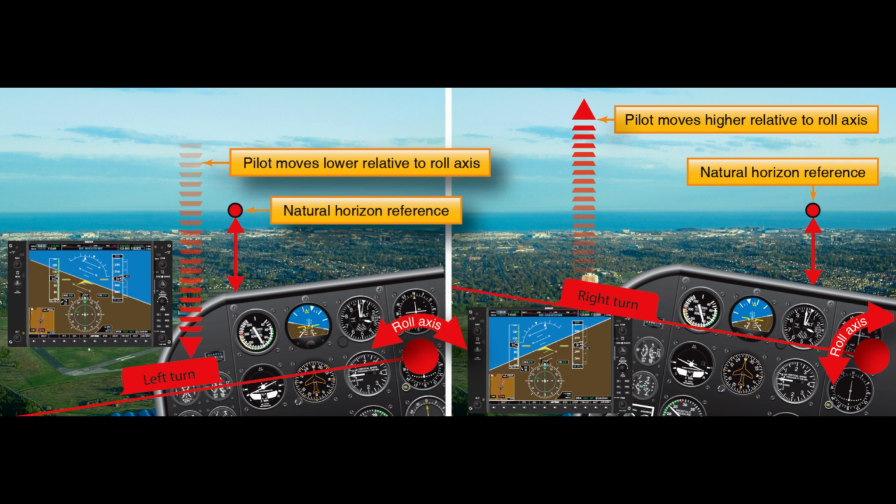A reduction in airspeed is the result of increased drag but is generally not significant for shallow bank angles. In steeper turns, additional power may be required to maintain airspeed. If altitude is not being maintained during the turn, the pitch attitude should be corrected in relation to the natural horizon and cross-checked with the flight instruments to verify performance. Steep turns require accurate, smooth, and timely flight control inputs.